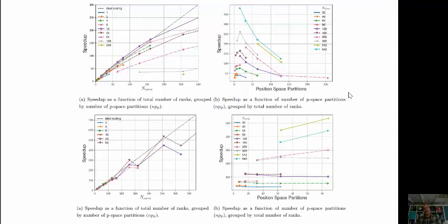But what's interesting then is if you change the discretization of the problem, so increase the fidelity of the problem by a couple of orders of magnitude. So I think in this case we went from 500 million to multiple billions of degrees of freedom. The behavior changes. In fact, we weren't able to push all the way to find where the optimum sits, because we didn't have sufficient cores available to us on the machine we were running at for this project. And in this case particularly, we see that the architecture of the machine has a big influence. So the number of cores per node has a big influence on whether or not you're achieving linear or, in some cases, superlinear speed up.